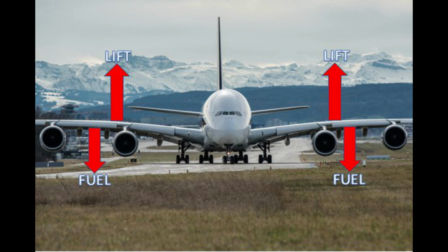Fortunately, the replacement of older, heavy electronic equipment with newer, lighter types results in a weight reduction. This weight change, however helpful, can cause the CG to shift, which must be computed and annotated in the weight and balance record. Repairs and alterations are the major sources of weight changes. It is the responsibility of the FAA certificate mechanic or repairman making any repair or alteration to know the weight and location of a change, to compute the CG, record the new empty weight and EWCG in the aircraft weight and balance record, and update the equipment lists.